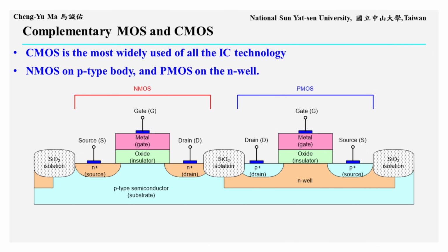Modern integrated circuit design mainly uses complementary MOSFET technology, called CMOS. This means that both NMOS and PMOS devices are used together in the same circuit. As shown in the structure, the NMOS device is built in a P-type body, while the PMOS device is formed inside an intentionally doped N-type well, called the N-well, on the same wafer.